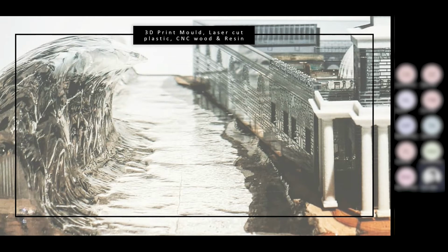And then for this wave, it's cast in resin. And this wave, I know for a fact because I worked on this. This one was 3D modeled in Rhino, and then it was subtracted from a block in Rhino. That block was then 3D printed and lined with resin-proof tape. And then it just had resin poured into it.